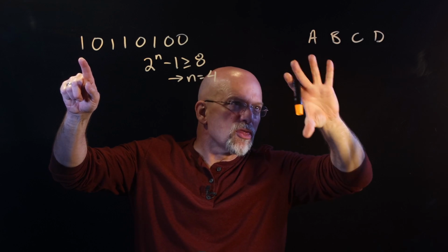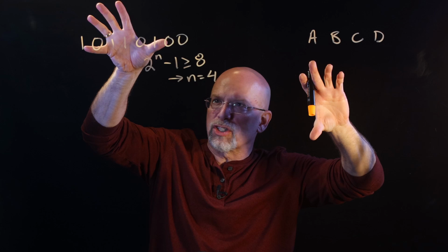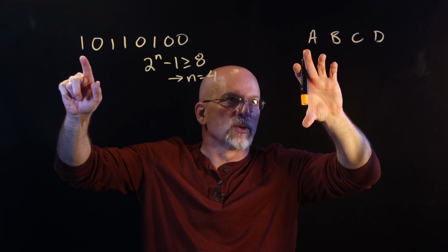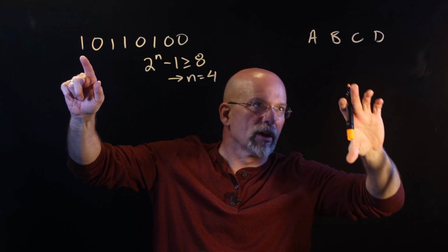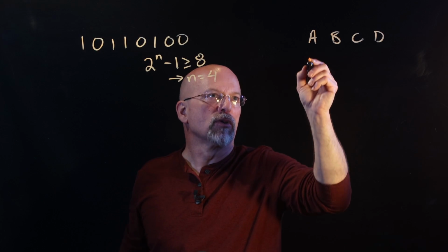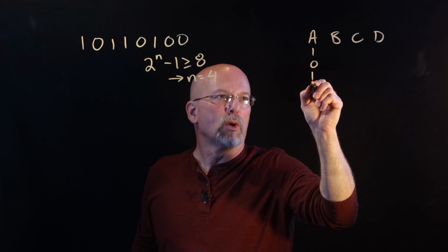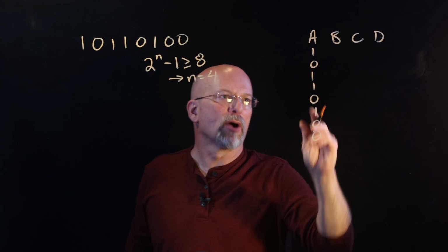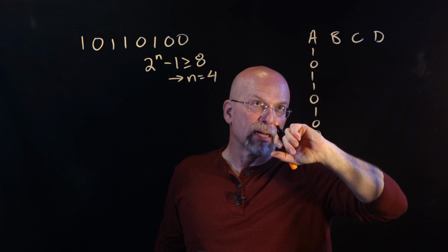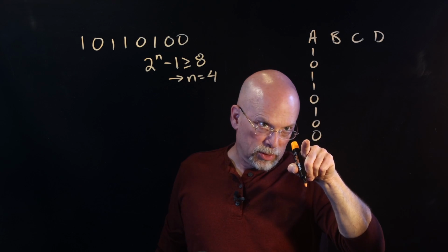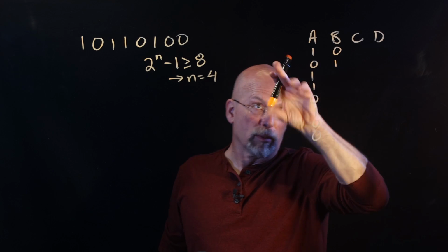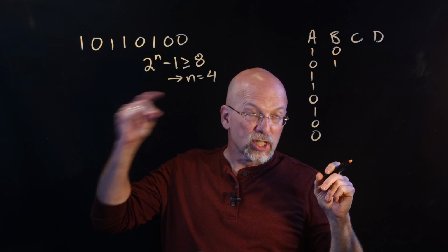So the sequence that's going to run through this, remember these are shift registers. So this sequence is going to run through these guys. And so each time we get a clock pulse, the sequence is going to go to the next cycle for each one of these latches. So it's going to start out, and remember the sequence can play over and over again. So we're going to do 1, 0, 1, 1, 0, 1, 0, 0. There is the sequence. If it's shifted so that the B gets the value of A at the next clock cycle, we'll take this 0 from the bottom, put it up here, and then each one of these gets shifted down by 1 cycle. Remember, each row here represents a single tick of the clock.